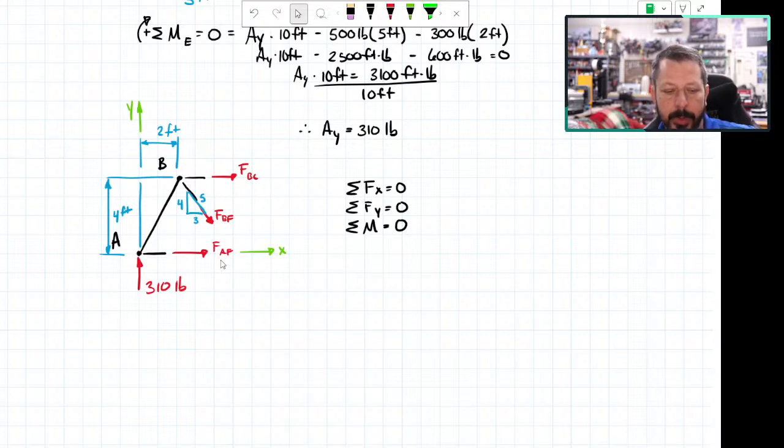So if there was a point where the 2 I'm not interested in intersected somewhere, like at a pin or something like that, then yeah, let's sum moments about that pin and solve for the one we're interested in. But that doesn't happen. BC and AF are parallel, so in our Euclidean geometry here, they never intersect.